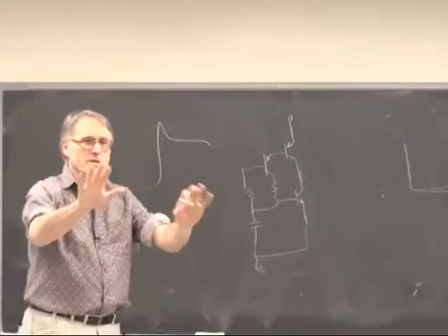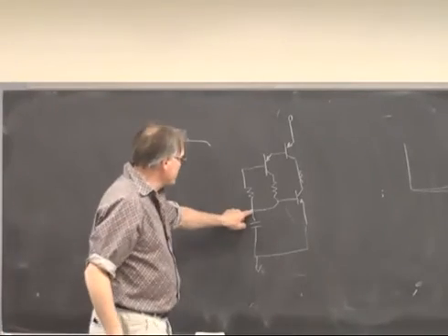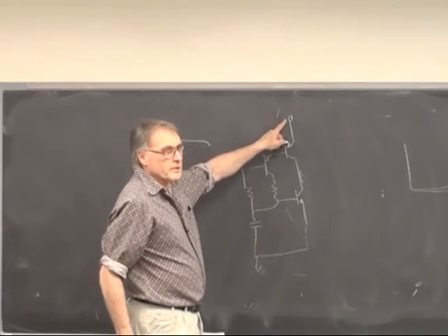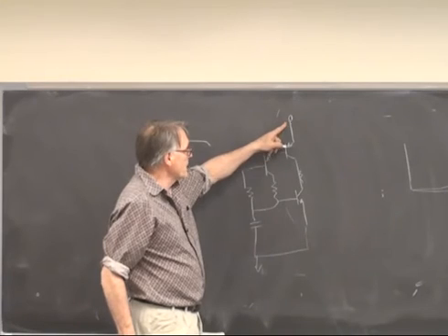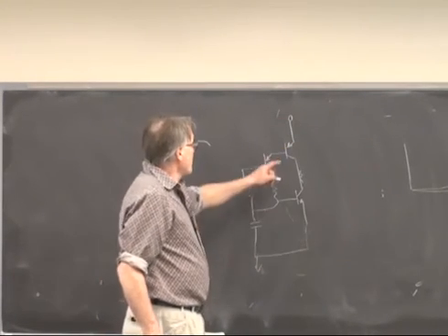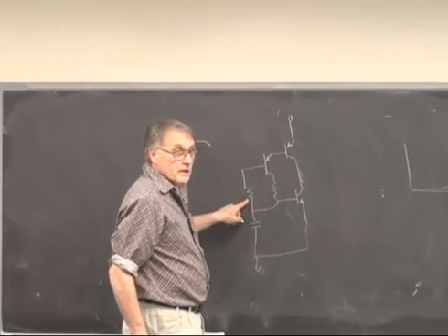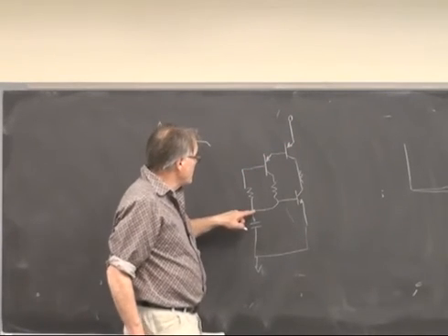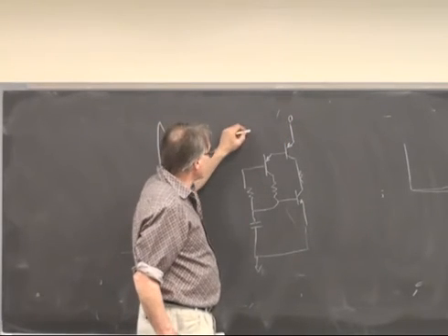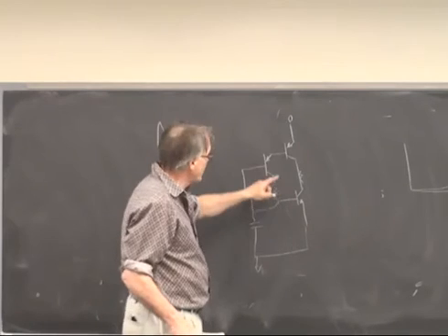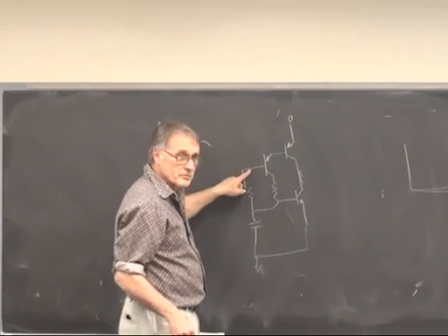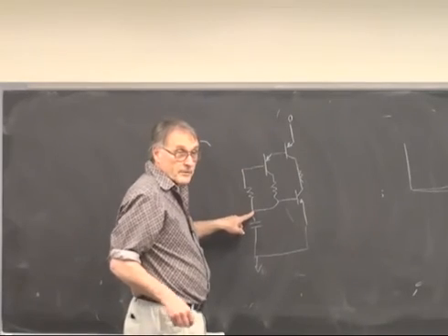So let's say we're starting at rest here. Voltage here is 0. You get some non-zero voltage up here as the system starts to depolarize. Both of these transistors start to conduct when the voltage here is about 1.4 volts, because you need about 0.7 to turn this one on, about 0.7 to turn this one on, and this point is at 0.